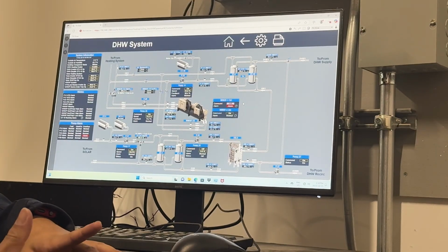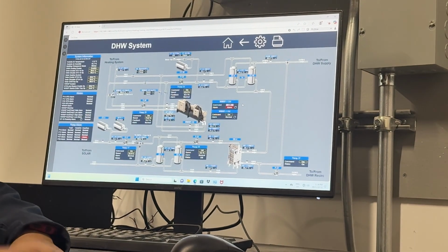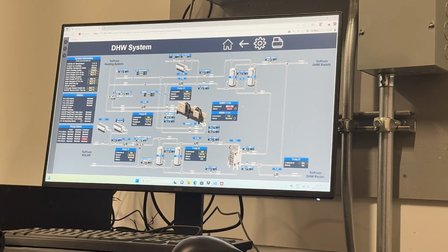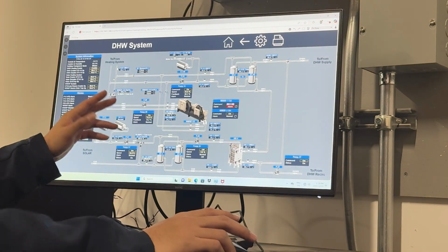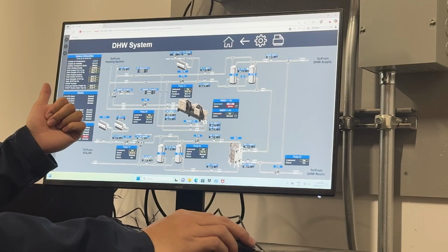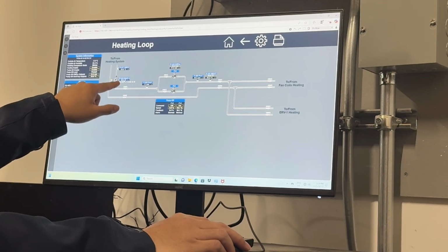So that means the boiler loop will take care of the domestic hot water. The reason we don't want the boiler to do the job is for energy saving, right? So we don't want that. As long as the boiler loop can do 52, we are happy. And that's also one of the reasons we have this three-way valve in place.